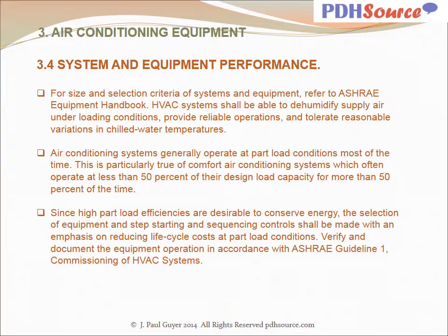Since high part load efficiencies are desirable to conserve energy, the selection of equipment and step starting and sequencing controls shall be made with emphasis on reducing life cycle costs at part load conditions. Verify and document the equipment operation in accordance with ASHRAE Guideline 1, Commissioning of HVAC Systems.